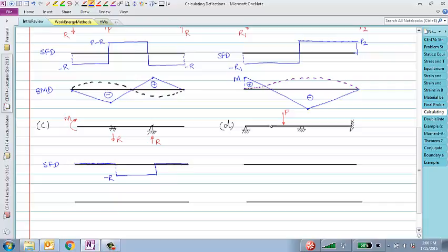And if ever there is a doubt, just go by equilibrium, Newton's laws, right? Newton's laws cannot go wrong. You cannot go wrong by doing that. It might be a slightly longer approach. Draw the free body diagram, assume the reactions, set up equations of equilibrium, and you'll see that the reactions come out that way. Okay. All right.